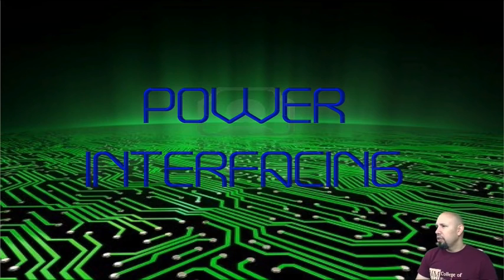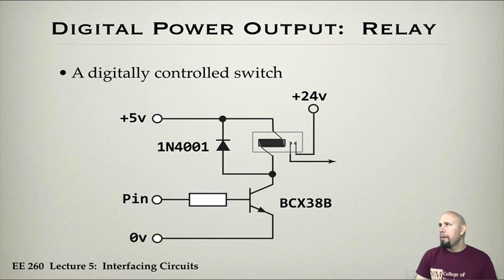Now we're going to move on to power interfacing. The first thing is a digital power output. So what are we talking about? The Arduino we saw can put out a maximum of 40 milliamps on any pin, or can take in 40 milliamps. For many applications, that's simply not enough current. So, for example, a motor, or obviously, if you wanted to hook up a 100-watt light bulb.